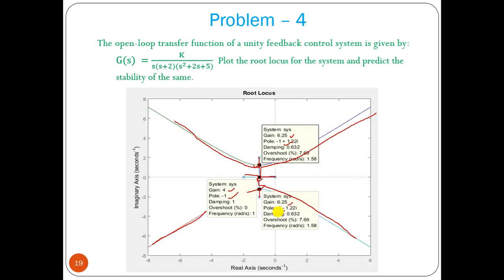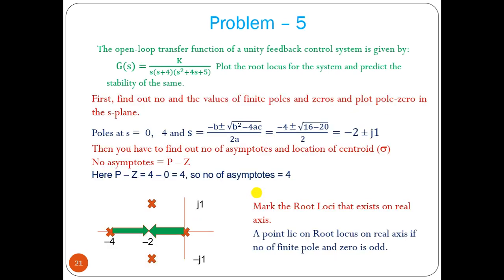So this is one of the most interesting problems. We can see here we have three breakaway points. We have seen two breakaway points in previous problems, which you can find in the root locus problem lecture video, and here I showed that we have three breakaway points, one real, two complex. So this is another most important point.